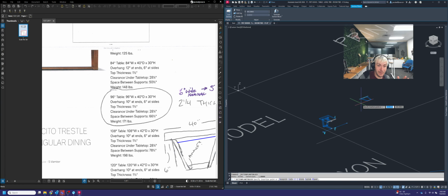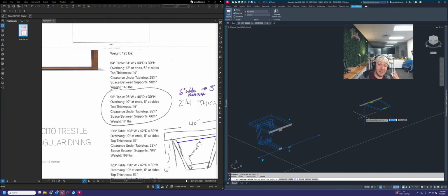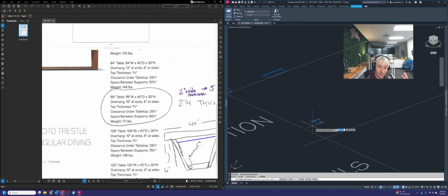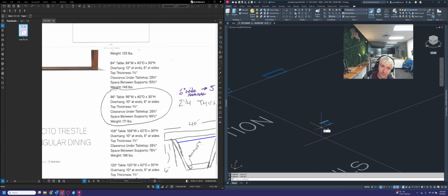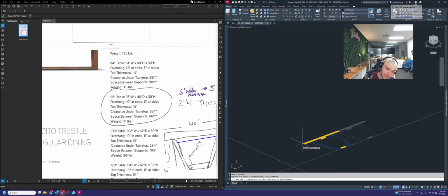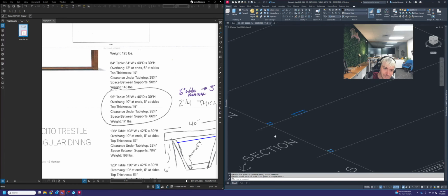You'll see it populate a section view based on the settings we selected. We're going to drop that over in our section view over here. So we're going to drop that and make sure our scale factor for X is set to 1, scale factor for Y is set to 1, and rotation angle is set to 0. So then we're going to move that view just like any other view. None of that changes depending on 2D or 3D drawing. It's all the same. You line it up with your grid, and then you're done.